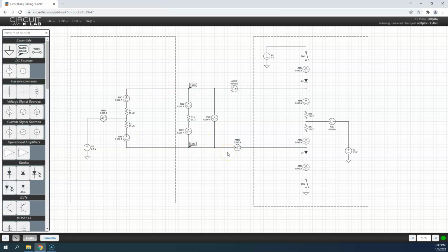That may kind of throw you a little bit. Maybe look at this, sketch it out, and see for yourself. There's no current flowing here. Everything's just being held at 2.5 volts. It wasn't until I put something in ground place, something that is grounded, such as that meter, that I could actually see some current flow.